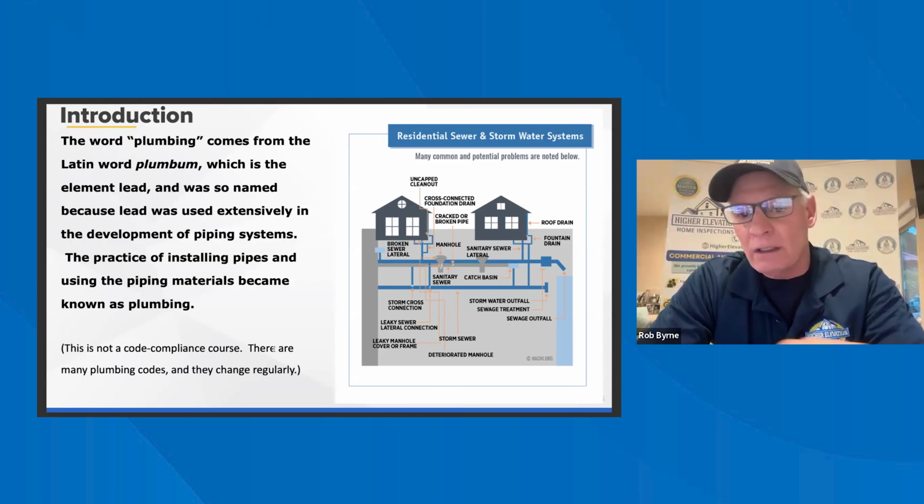They say if you have a lead water main, run the tap for 2 minutes and it's going to clear it out, but it's all your level of comfort when you have a lead pipe. It's our job to call that out if we see it. So make sure you know how to go about inspecting a lead water main. If it's coming through the house, everybody should know how to do that. That's important.